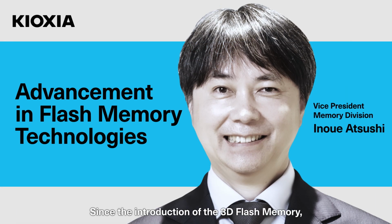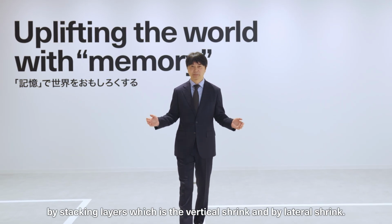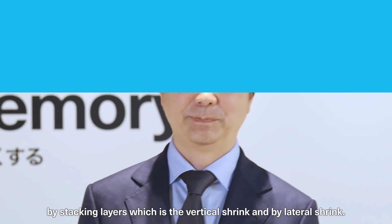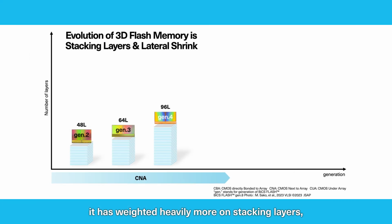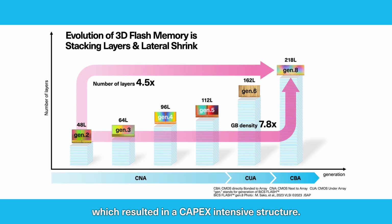Since the introduction of the 3D flash memory, the prevailing paradigm in the industry has been to shrink the die size by stacking layers, which is the vertical shrink, and by lateral shrink. But over the past few generations, it has weighted heavily more on stacking layers, which resulted in a CAPEX-intensive structure.